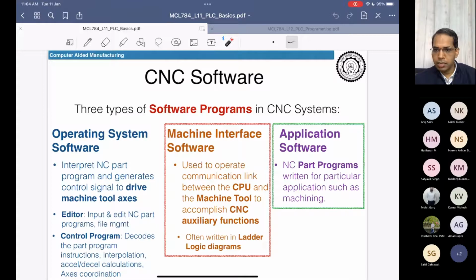I'm sure that all of you have seen a CNC machine somewhere, and you will be entering some part program into the machine controller. Now, if I write a simple instruction of, as I was mentioning, N10 X15, how will this program get executed? How will the machine understand this program, and once it understands that you want to give a displacement in the X direction of 15 units, and most of the time these units are millimeters or inches, how will the machine controller execute that motion? That is an important part to understand.